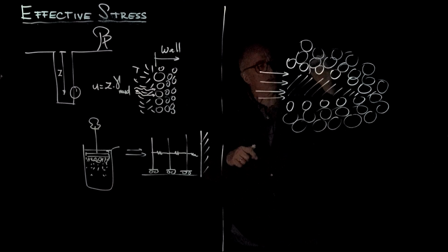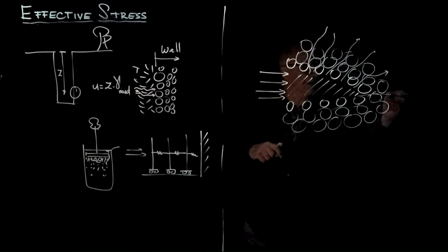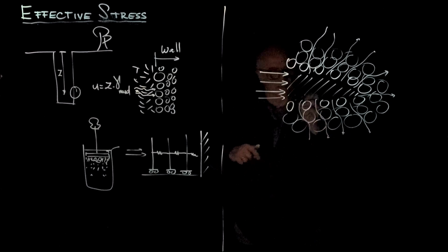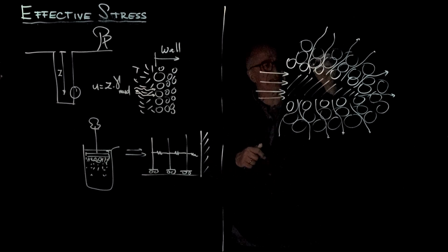But if you see, water is leaking through here, and as it leaks, it's transferring that fluid pressure onto the grains by drag. And so this first grain doesn't have any effective stress. It's against water. But it's picking up the drag, and that, by equilibrium, is transferring that from the drag onto the grain, onto the next grain.